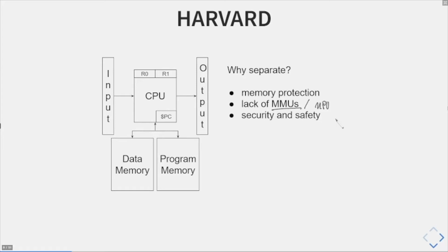These memory protection units, this is something that you can learn about in the operating systems lecture. This is basically an indirection between the memory access. So instead of accessing memory directly from your program, you have another table in between that gives you a little bit more control of which program or which part of your program can access which kind of memory.